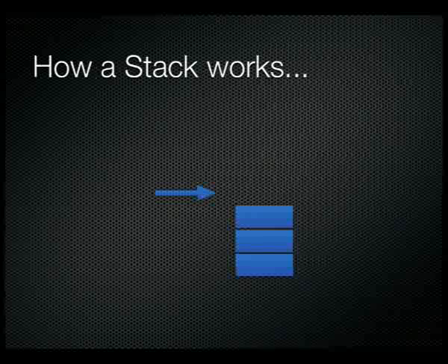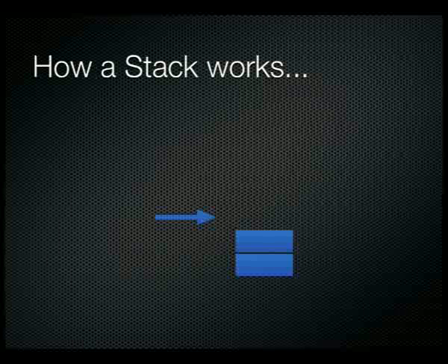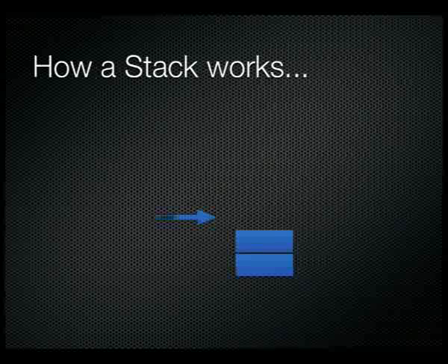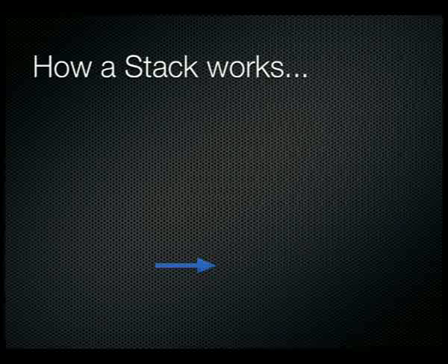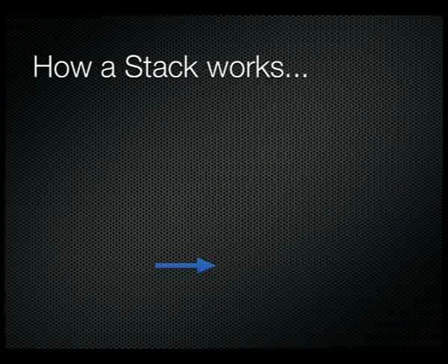Like a stack of books, the processor stack works in the same way. If you want to get, say, the book that's fifth down, you've got to pop all the values off on top of it before you can get to it. So a stack on the processor works in the very same fashion as a stack of books or a stack of plates. It's last in, first out. The last one you put on the top is the first one that you're going to get off the stack. We grab the last one off, and we just keep our pointer pointing to where our space is that we can stack our data or variables that we might want to be using. We'll talk more about the stack operations later on when we talk about the instruction set.